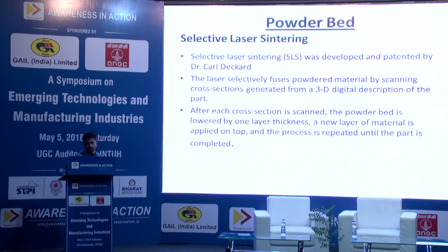So next comes the powder bed, which is nothing but the SLS technology, selective laser sintering. Even in this, the laser is used, but instead of resin, in the reservoir, I keep powder, basically. It can be nylon powder or ABS powder, any kinds of powder. And this powder is also not the normal powder. Basically, the crystal sizes are predefined. So it is not that random crystal sizes are kept in the vat and then the selective laser is done. No. These powders are also special. You get these materials from certain manufacturers only.